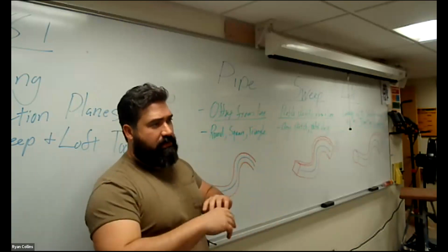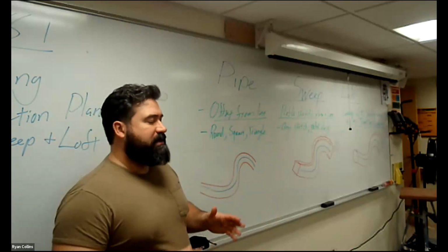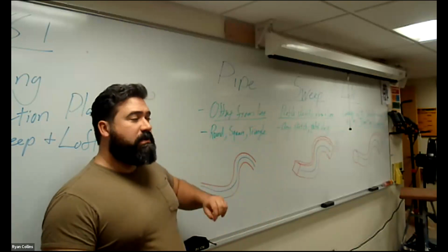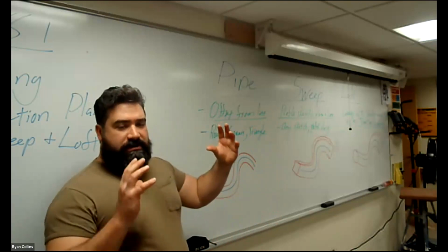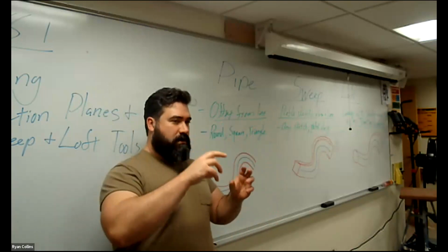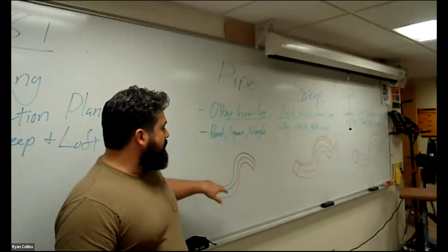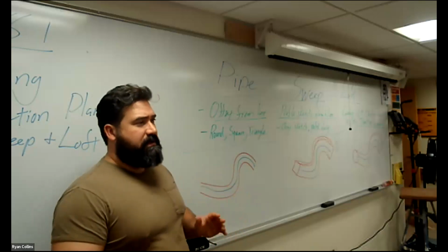You can push and pull that around in three dimensions as well, although it takes a little more manipulation. Don't worry about it. Then you can use the pipe tool and generate pipes around that, so you don't have to shift and move three-dimensional rods or cylinders into place. This is a really convenient way of making three-dimensional cage forms.